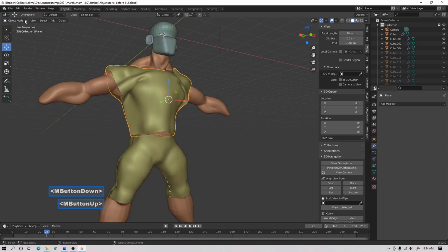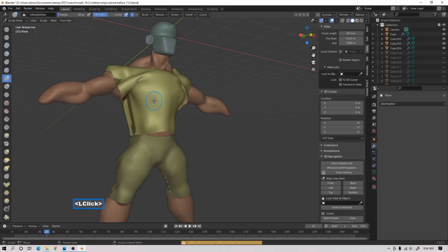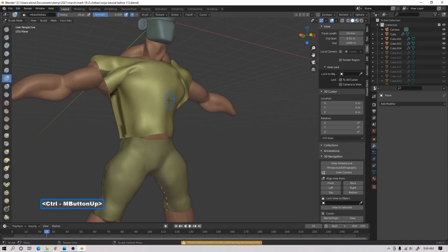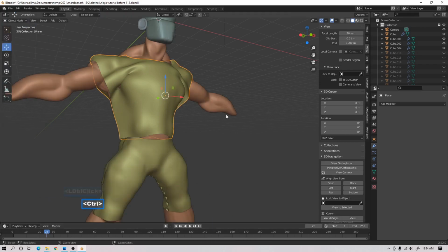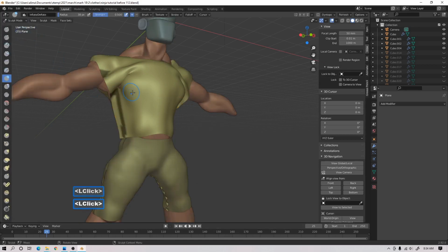So let's go to sculpt mode. Well, this is showing up saying it's not uniform, so we'll hold Control, press A, select all transforms, go back to sculpt mode, hold Alt, press M to take off the mask tool. I'm holding Shift.